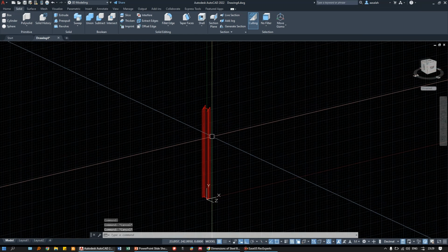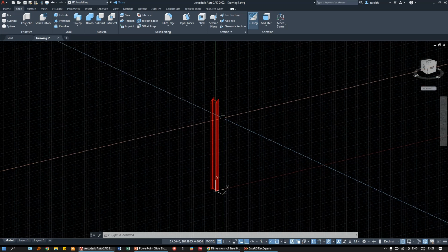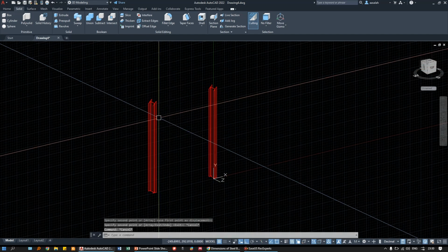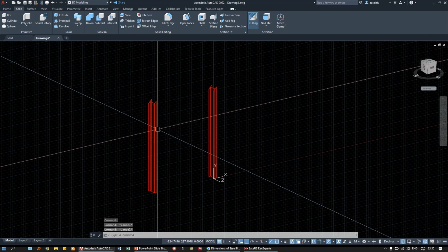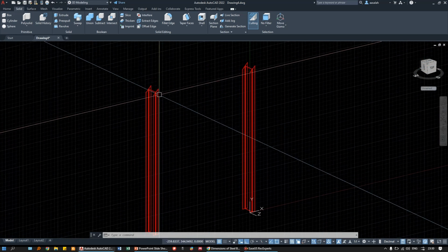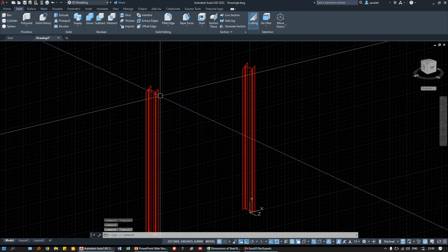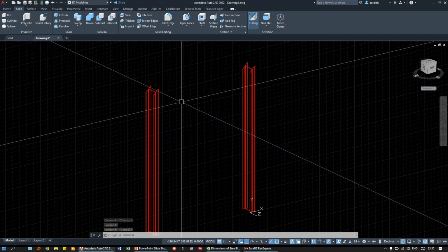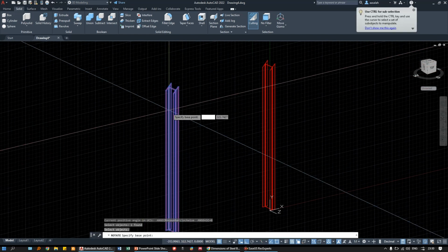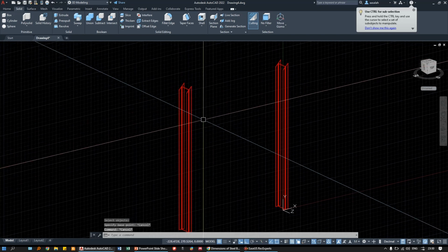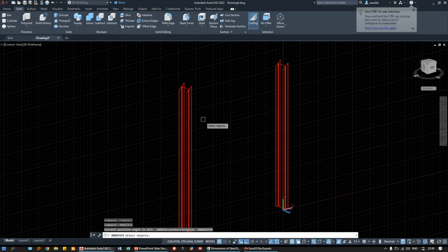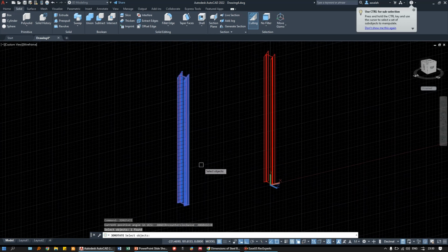Let's assume we need to bring this I-beam now. I'm trying to form a 2D frame, but it's kind of not realistic. But let's assume that I want to select this I-beam, and then I need to rotate this beam. Now I will explain some things about rotation commands for the 3D models. Let's assume we have this beam and I want to switch it so the slice cut needs to face the other slice cut from here. So when I select this model, I cannot simply use the rotation command because rotation works only in 2D. So I'm going to select the 3D rotate command,